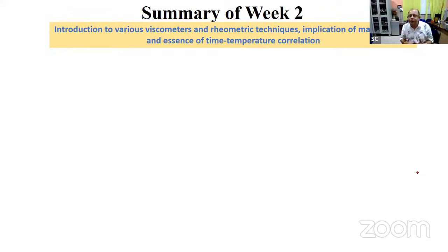There are other mathematical equations available by which you can overlay your measurements from different rheometers, apply the appropriate shape factor, and lay them on the master curve. This conception is quite common, whether you do it for a DMA, which you call TTS, for example.